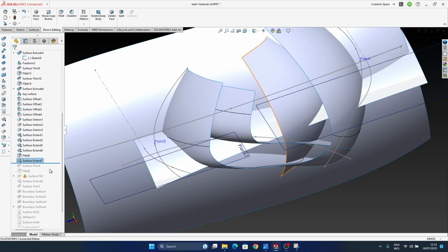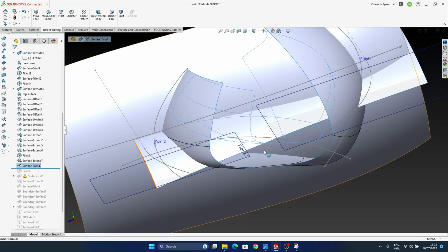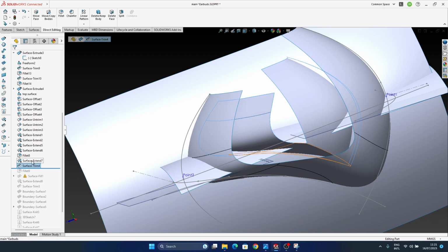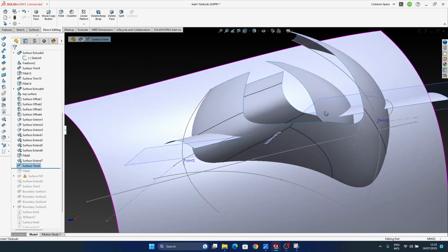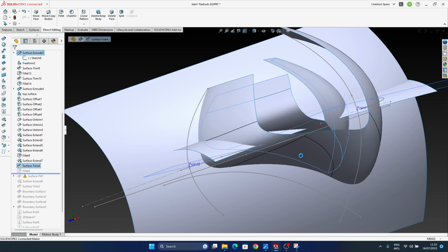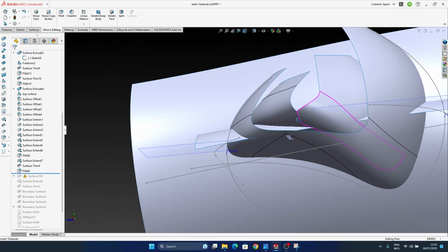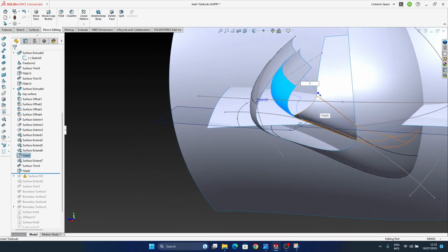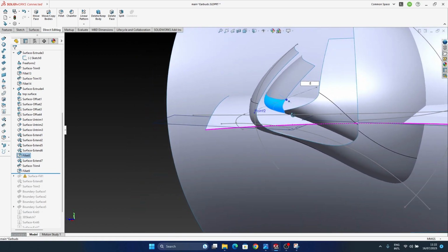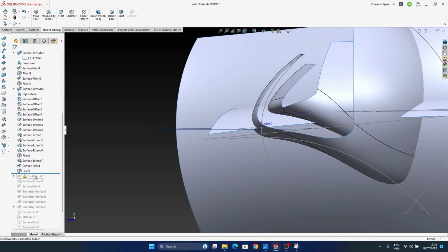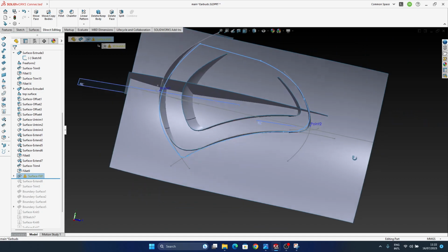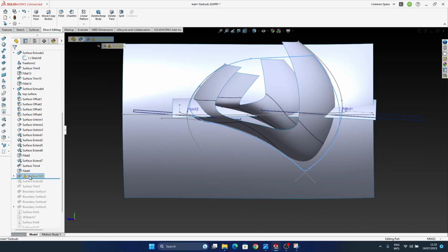Could be so nice if Solidworks could just show me which edges I did before, but it doesn't. So I'm having this trim in here because, again, last time, if you remember, I had some issues doing the fillet, so I applied the same strategy. And then I'm doing this fillet in here. Right, this one in here, it's a bit too big, so I would say maybe 2 millimeters would be better. Okay, and then we have a surface fill somewhere. Let's see where.